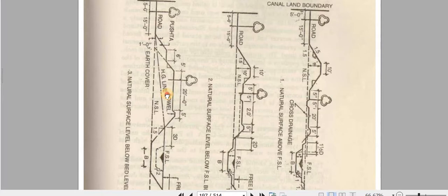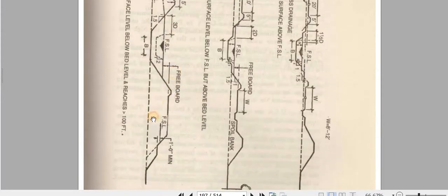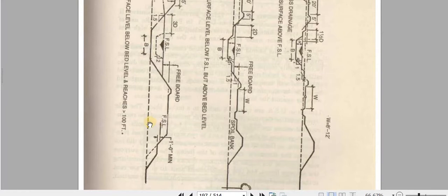In our dam design, we will study this hydraulic grade line: if water seeps, it should not come onto the road. It should not create any ponding or any surface runoff on the road. So we have to increase the embankment height and length in this case. You can see here we have less, here less, but here we have more in both cases.